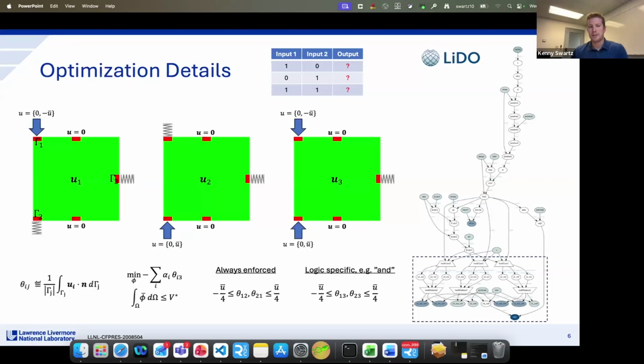Yeah, I think the main thing is the bistability in the inputs. I think these are compliant mechanisms. They are creating the type of deformation that we want by elastic distortion. I don't know how exactly you define a compliant mechanism, but I would say these are. The main thing that we're doing here is the digital logic part, which I think is unique, where our inputs snap between two distinct locations. The mechanism has to push hard enough on the output to get it to go into its second well, and there is the discontinuity and the gradient problem that presents, while trying to satisfy this complex logic. But I think these are just difficult compliant mechanisms.